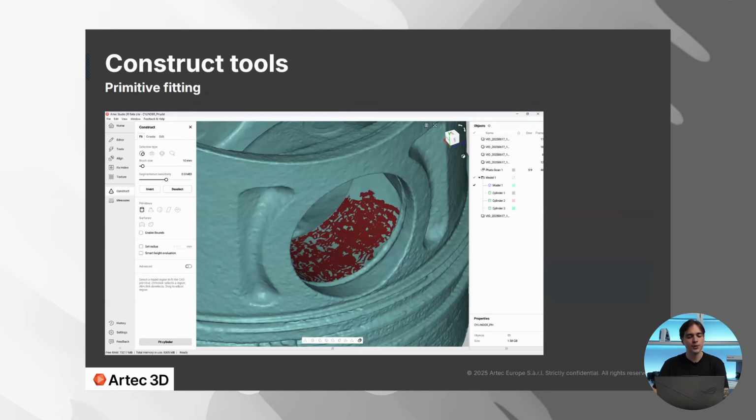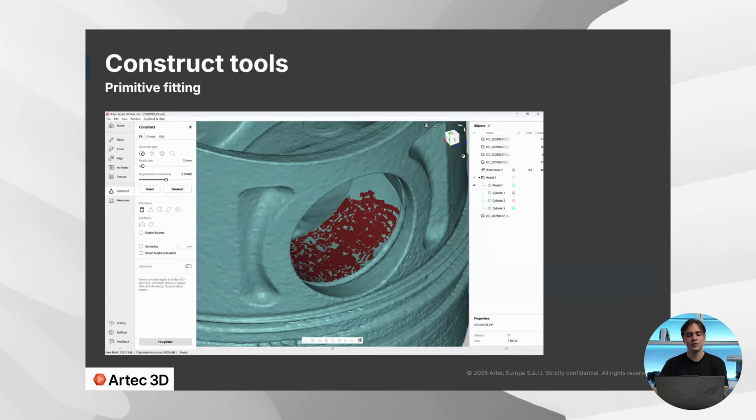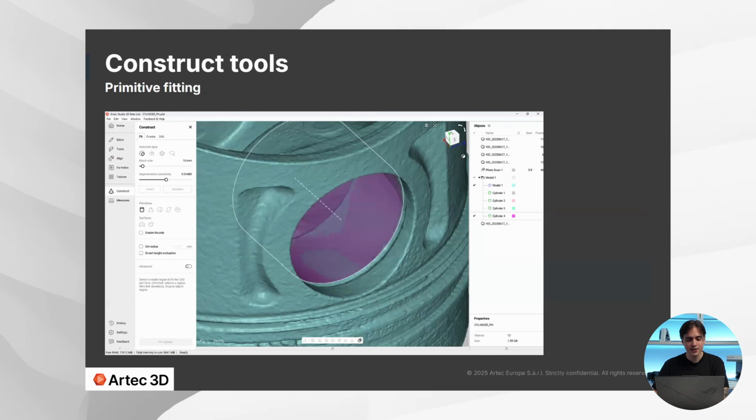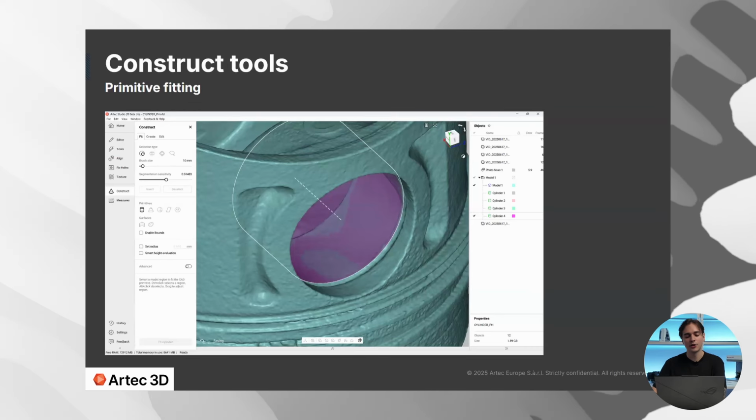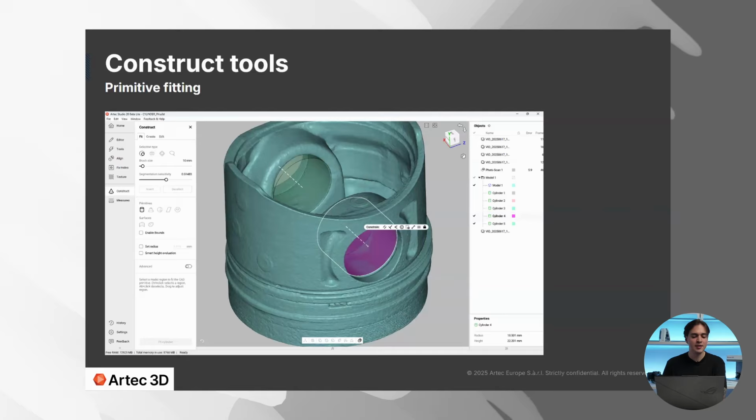Then we have the Construct tools. We have primitive fitting. So let's take a look at this on the example of this industrial part, a piston that we've scanned. Here I have defined an area on the mesh, and then I fitted the cylinder into it. As you see, this cylinder has been fitted pretty accurately in this cylindrical feature. And then we can get the measurements out of this cylinder. We can get the height, we can get the radius.